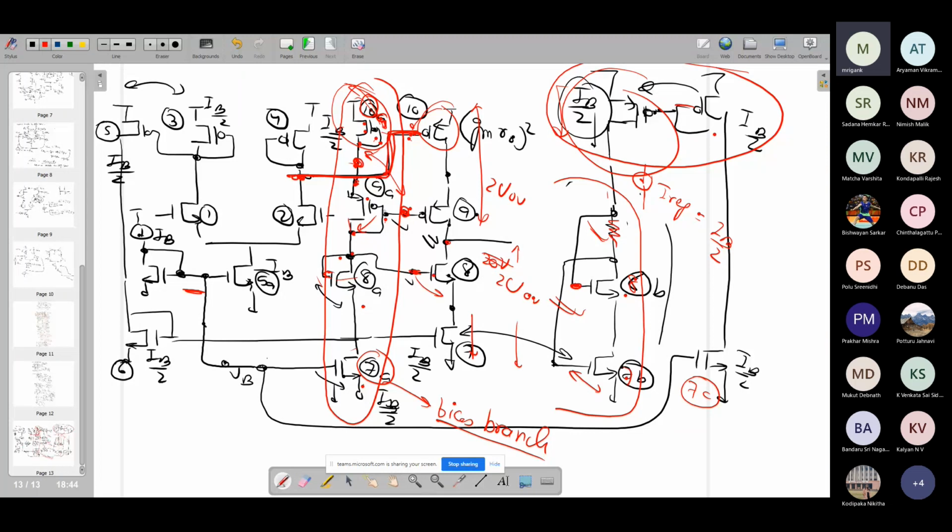I need to generate the appropriate voltage for M9, and for that I am using the same transistors as M10 and M9 in this branch, pushing the same current, so that I get the two values of VSG generated in the stack, and then I bias the gate of M9 with that. M10 does not need a bias because it is connected to the output of the first stage, which takes care of the DC bias. But M9 does not have a DC bias. For that, I am generating the required gate voltage with the help of these four transistors.